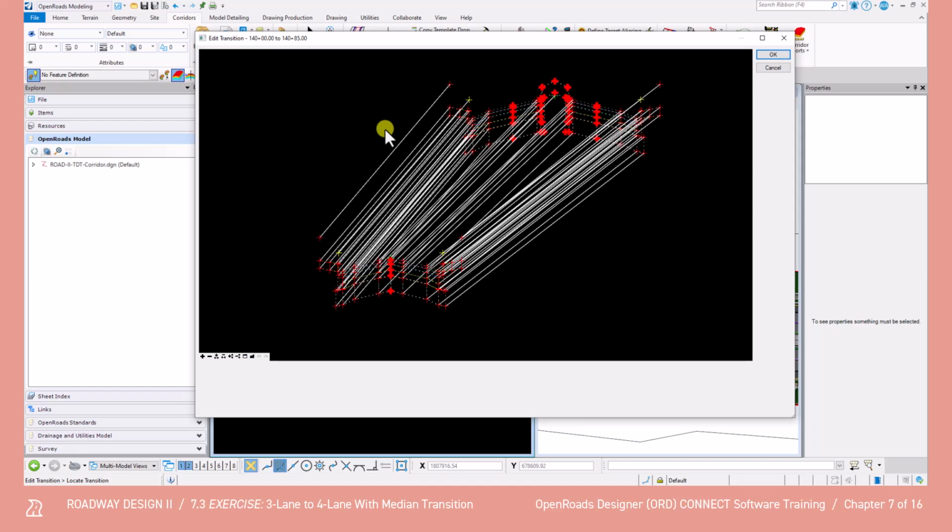The recommended workflow for connecting points from one template to another is to work from left to right and bottom to top. It is not necessary to connect every point, but this enhances the ability to properly model a transition. To navigate the lines more easily, it is beneficial to align the templates vertically to each other by right-clicking and selecting the Move Template.